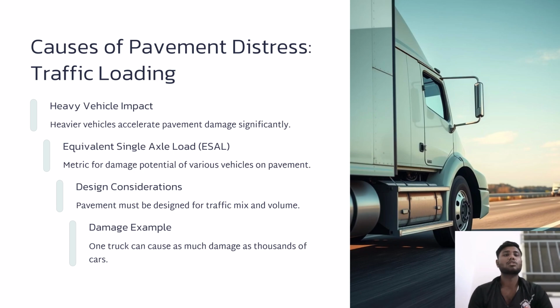The next one is causes of pavement distresses because of traffic loading. Because of traffic loading, heavy vehicle impact causes distress. Heavier vehicles accelerate pavement damage significantly. The equivalent single axle load (ESAL) is a metric of the damage potential of various vehicles on pavements.